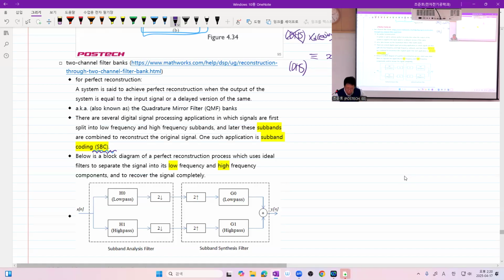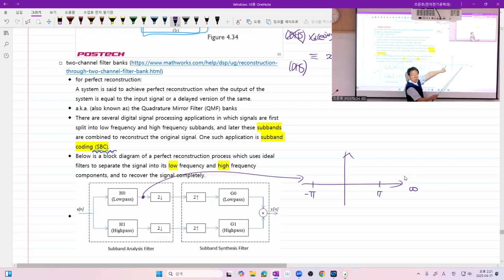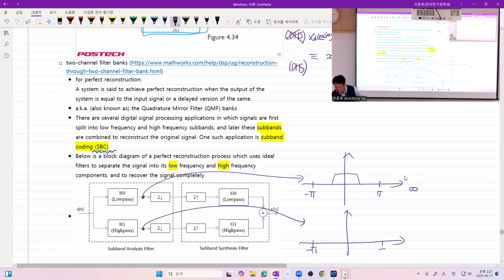And in the frequency domain, what do we have here? Of course, the DTFT is periodic, but we may say this region close to plus minus pi is the high frequency part. So this signal after low-pass filtering will reside around here only. Similarly, you will have the output at that part looking like this. Now, you find a lot of space there, right? Which means you may reduce the sampling rate by downsampling. So here goes downsampling.